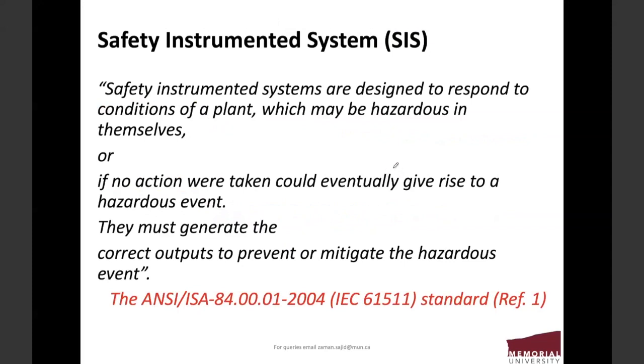Out of all these layers, the detailed work in your course is based on SIS, which is the Safety Instrumented System. Safety instrumented systems are designed to respond to conditions of the plant which may be hazardous in themselves, or which, if no action were taken, could eventually give rise to a hazardous event.